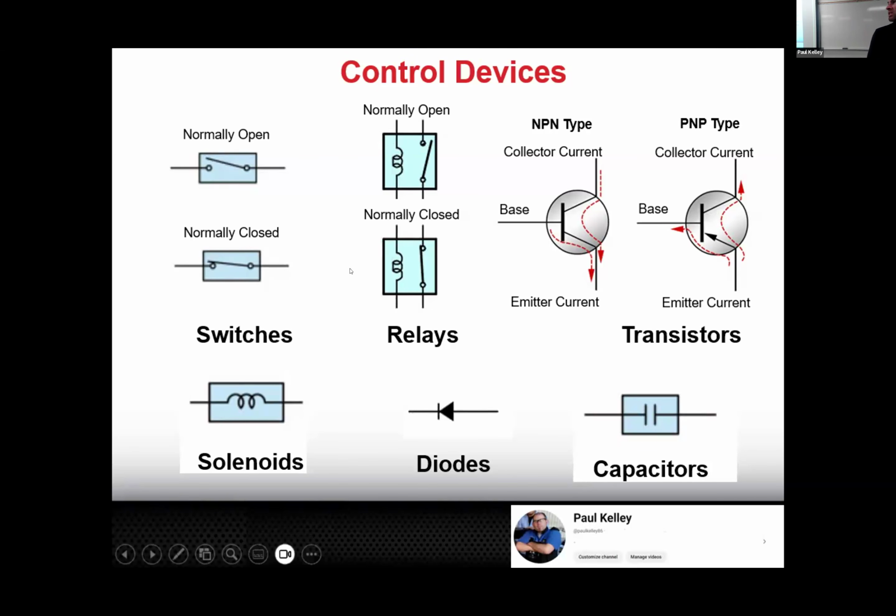Like for example, maybe it's an anti-theft system that, if you go to start the car, this should be normally closed, but if it detects that you don't have the correct key or something, the ECM can give 12 volts and ground, which will force the relay open, which will stop power from getting to the starter, and therefore you can't steal the car, right? So there's some instances where we may want a normally closed relay that we have to actually force open for something, to interrupt power, to interrupt somebody from starting the car and stealing it, right?